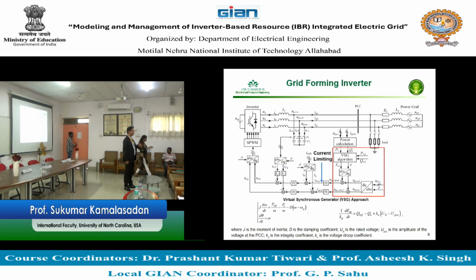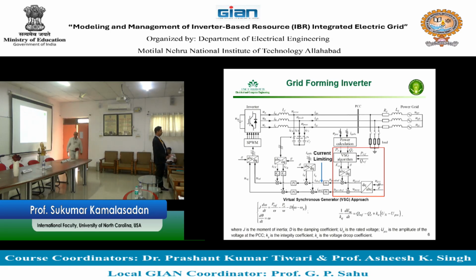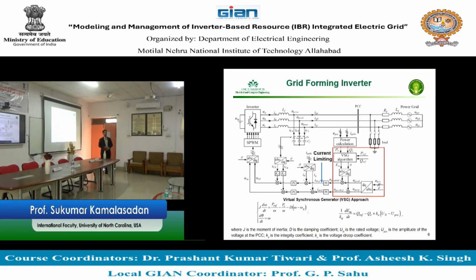It's called the 8th order model of the generator. It is the largest generator model that we have. So 8th order means, how does the order go up? Order goes up depending upon the differential equations which you have. So one way to emulate the synchronous generator is to go all the way up to 8th order.